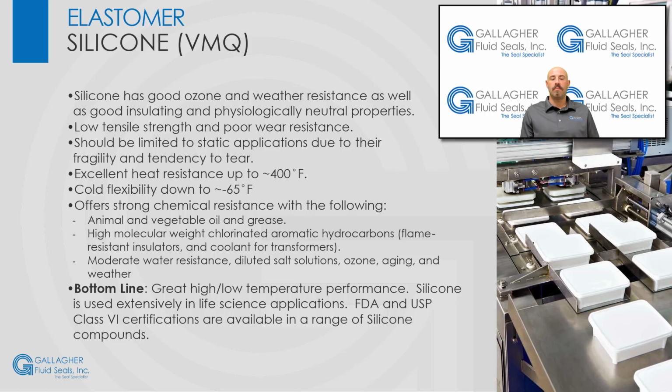Silicone is not compatible with the following: superheated water steam over 250 degrees Fahrenheit, acids and alkalis, low molecular weight chlorinated hydrocarbons such as trichloroethylene, hydrocarbon-based fuels, aromatic hydrocarbons such as benzene and toluene, and low molecular weight silicone oils.